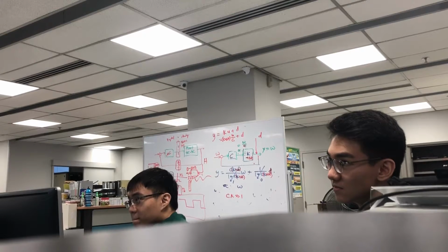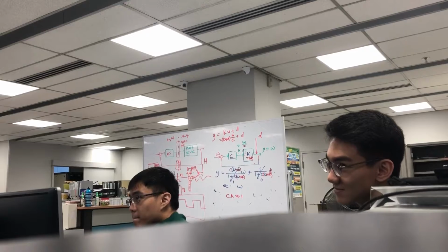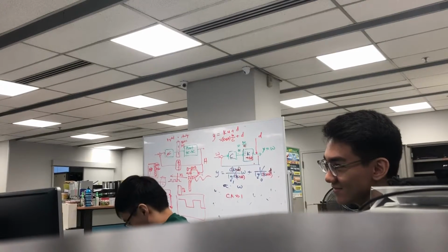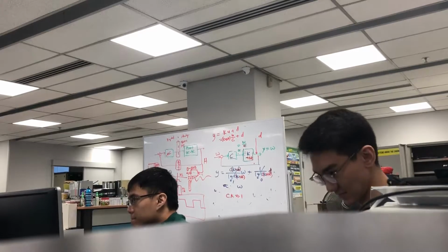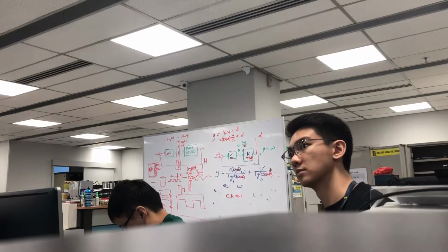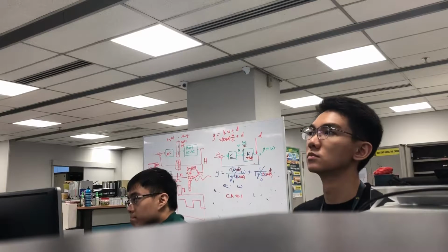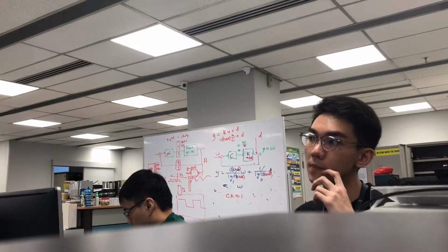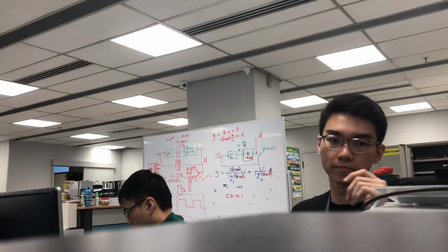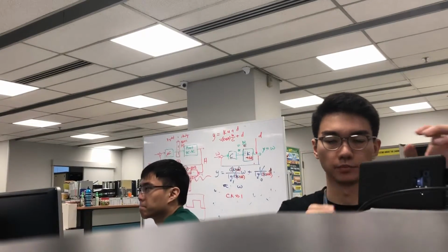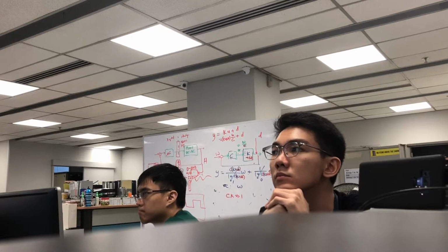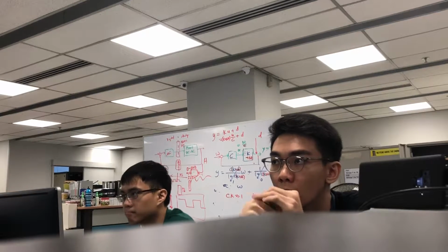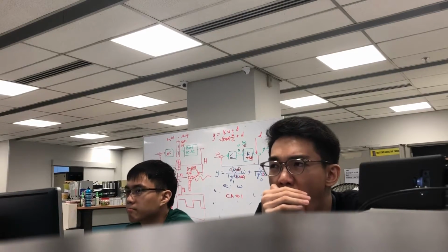So here is a simple demo program. You write to pin X, whatever it is, not important. High, and then delay. Delay is a built-in function of the compiler. In this case, we give you a 1 millisecond delay, and then you set it to low, and then you delay for 3 milliseconds, and then repeat. So you can imagine what you expect to see on the scope, and then you confirm it.